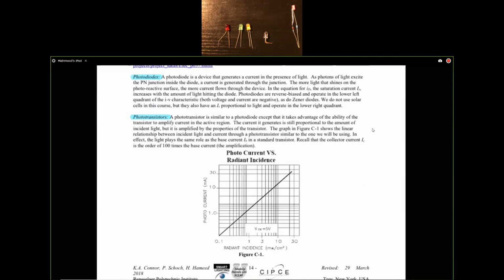And as you know, the transistor operates in three regions: the cutoff region, active region, and the saturation region. If we are able to operate that transistor in an active region where it functions as a current amplifier with a gain of around 170 that we explored in experiment 6, we can get a large amount of current, or photocurrent, to flow through our phototransistor.